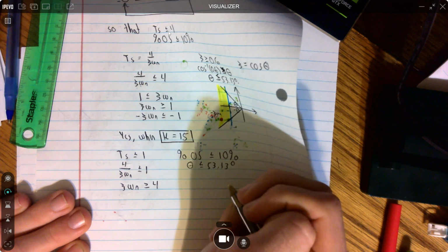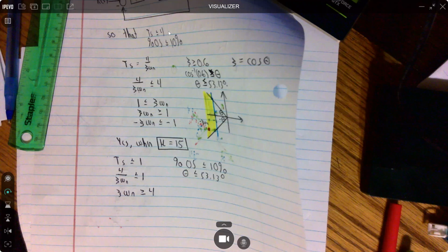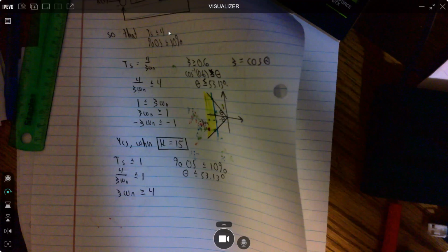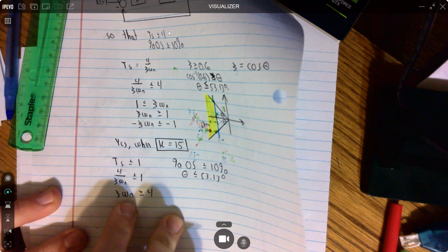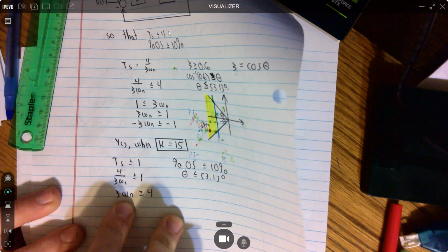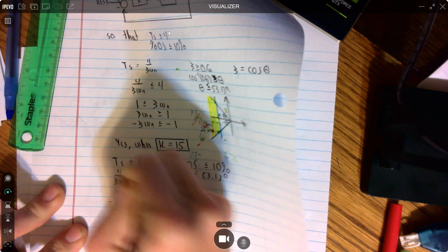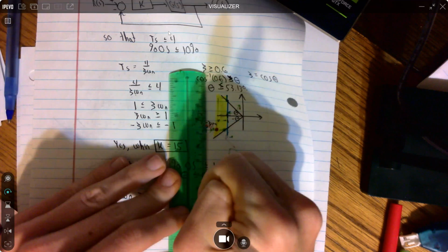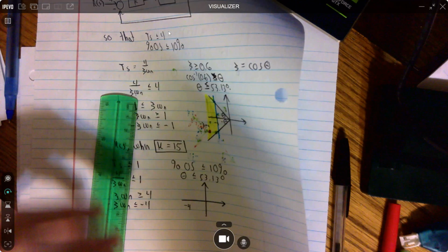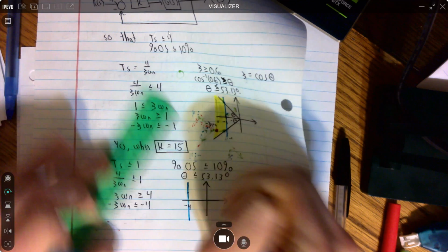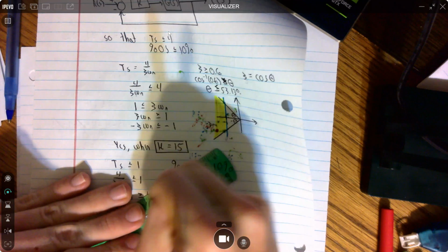And then here, oh, give me a second real quick. So here what we need to do is our settling time. If we have to have our zeta omega n greater than or equal to 4, looking now when you apply a negative, it flips the sign here to -4. And so graphing this now, at -4, this is your new condition where you have to be past. And so we still have the same angle, which is 53.13 degrees, so about here is our angle.